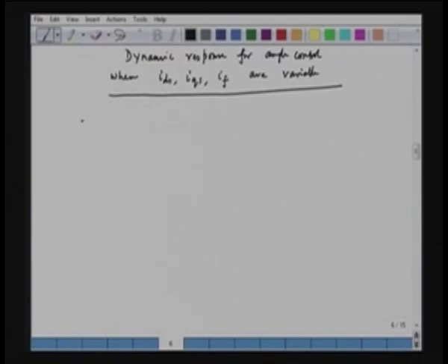We have the field current here, IF, and then we have the D axis stator current, plus and plus. Then due to the change of these two currents, we will have IKD. So, IKD will come up because these currents change, LMD P by RKD plus LKD P, and this is IKD.